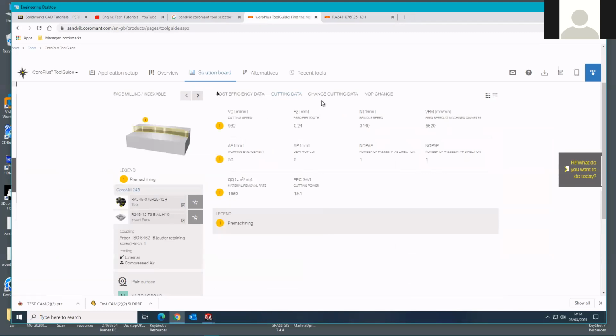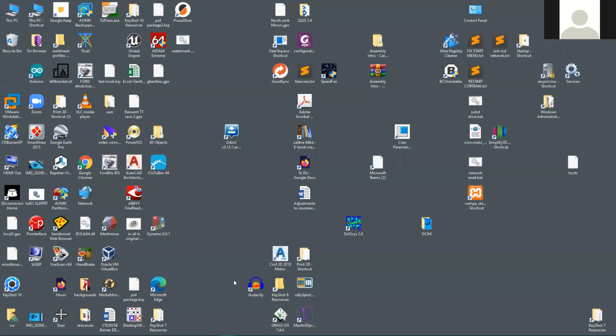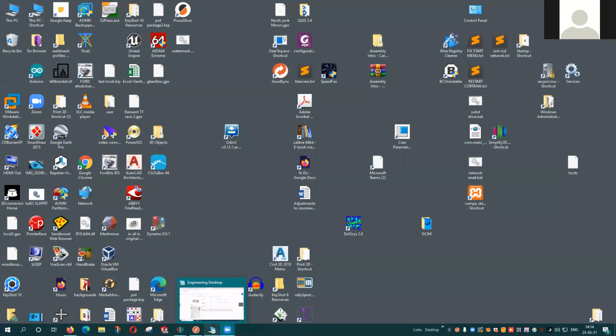So this is giving us data that we can then feed in, in terms of setting our rotational speeds and how quickly we push the tool through the material and how deep we should be taking for each cut, or each pass that we do on the material. Working engagement is what I was talking about before. How much of the tool should actually be doing cutting work?